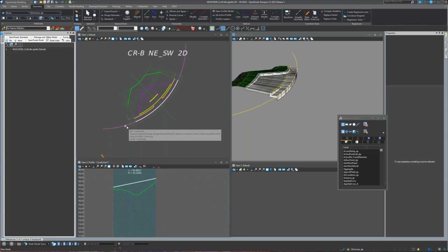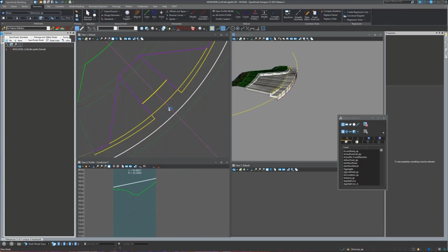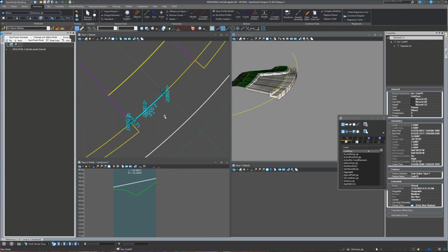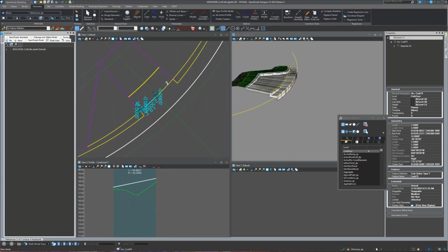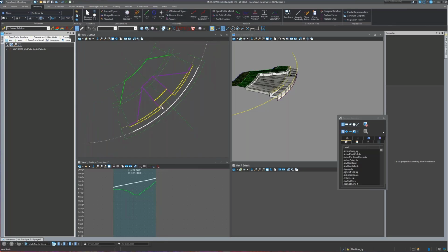So these are my two reference lines. So everything else is sort of built off of those lines. And if you've seen any of my other videos, I use a ton of construction lines, and this is kind of why, because I'm basically trying to make sure that all of this stuff gets ruled properly. So the way a lot of this stuff is set up is I've got a 2 foot 5 inch that way, 2 foot 5 inch that way. So I'm basically making sure I have a 5 foot landing down here. And then that's kind of what sets up all of this stuff.